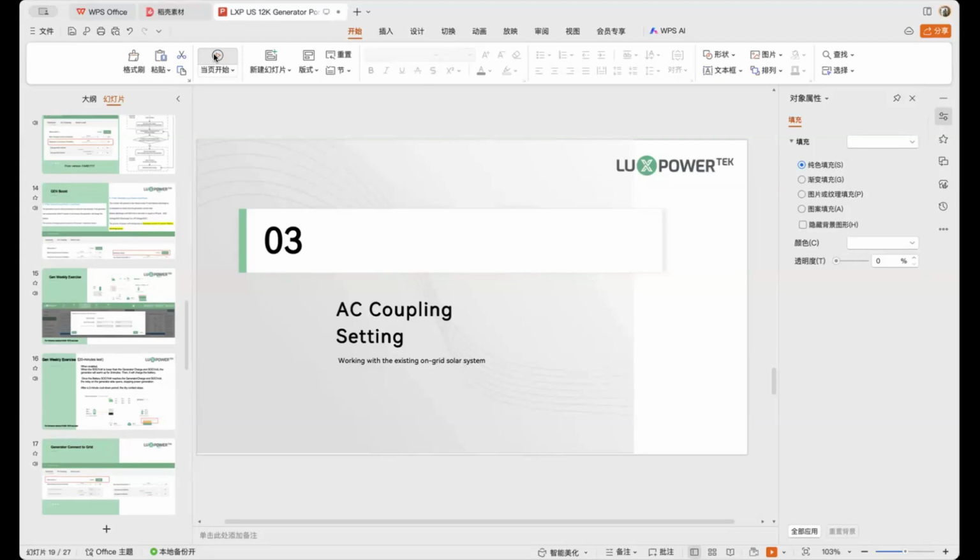our system. So as shown, there is a relay. We will close the relay. Then the AC coupling power can go to the inverter. We can see that here in this system now, if the SOC is very low, you can see it starts the AC coupling system.